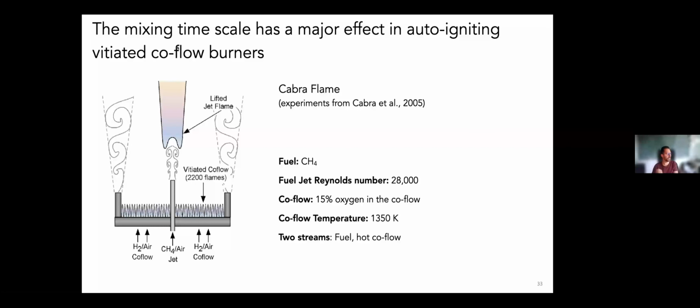The important thing here was that we wanted to have a challenging case to test the impact of these local mixing models, in particular the impact of uncertainties in the turbulent dissipation rate transport equation, and in the dissipation rate transport equation for the scalar that we use for the evaluation of the mixing time.